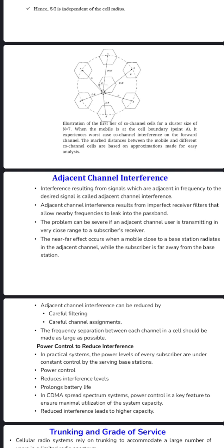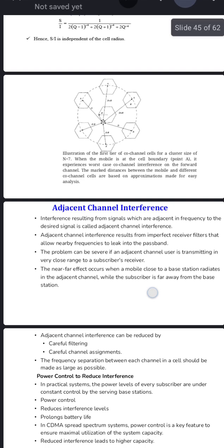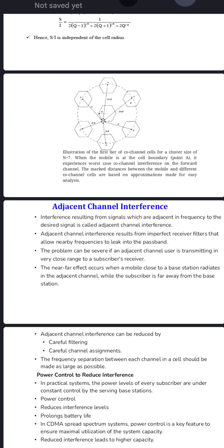If you see the relationship between interference and capacity, there will always be a trade-off between interference and system capacity. Increasing frequency reuse increases capacity, however, it also increases co-channel interference. Increasing the distance between reused frequencies reduces interference but also reduces capacity. So our goal in cellular network design is always to balance capacity and interference.